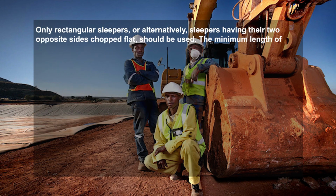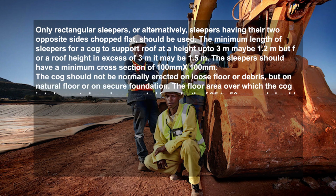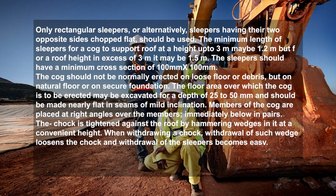Only rectangular sleepers, or alternately sleepers having their two opposite sides chopped flat, should be used. The minimum length of sleeper for a cog to support roof at a height up to 3 meter may be 1.2 meter, but for a roof height in excess of 3 meter it may be 1.5 meter.